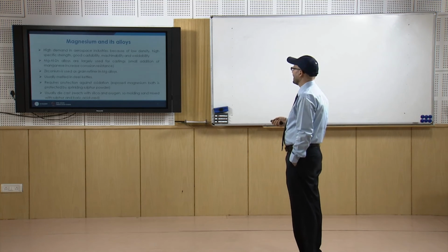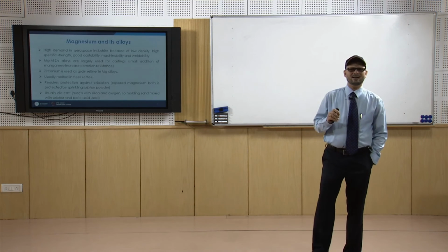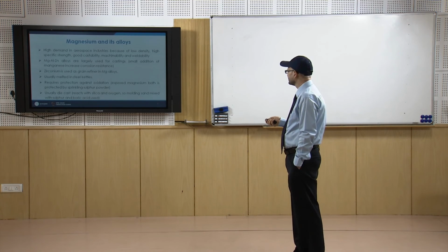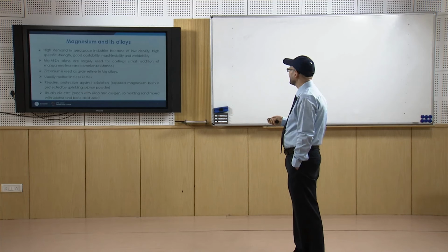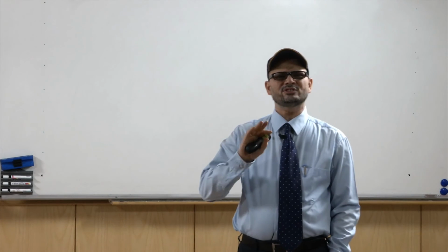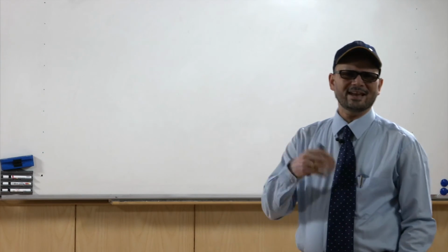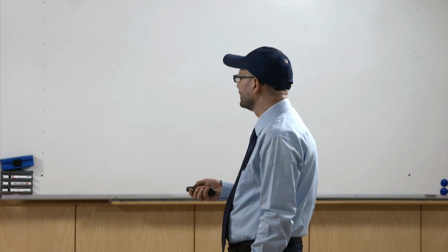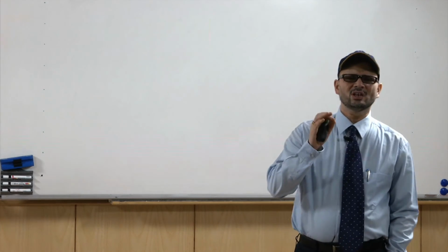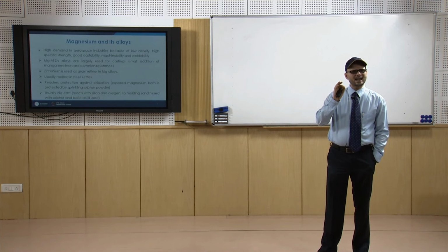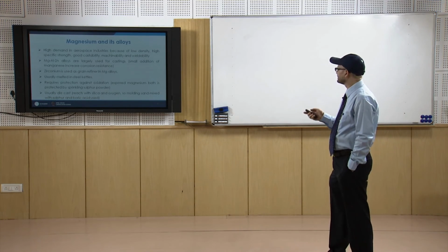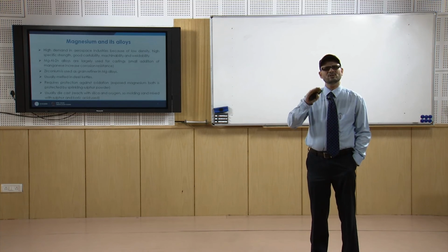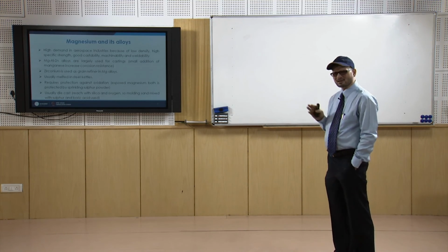Now, these materials are normally die cast. So, casting is done using the permanent mold casting, because the reason for this is that it normally reacts with silica as well as oxygen. So, as we know, with silica as well as oxygen, it is highly reactive and it reacts. So, another practice which is common is that the molding sand is mixed with sulfur and boric acid. So, if you use the sulfur and boric acid in this molding sand, in that case there is high probability that there will be no reaction of the silica and oxygen, and you can use the molding sand molding process for casting of this magnesium.